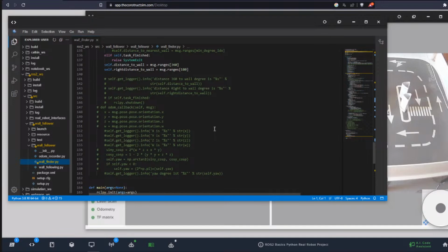And there's something going on maybe in that Z angular yaw measurement of the odometry, because we saw that the X and Y work really well, because that's what you use to go around, detect how long you've gone and print it out. That works. Now that you mention it, you're the second person now, so I'm going to take a look, because it might be a sensor that's out of whack, and that's why it wasn't working in the real robot.